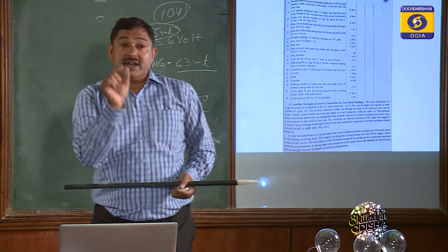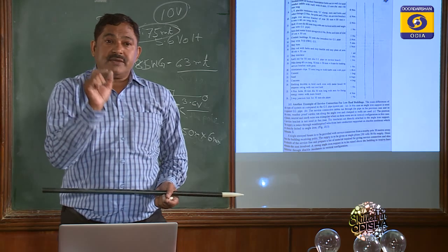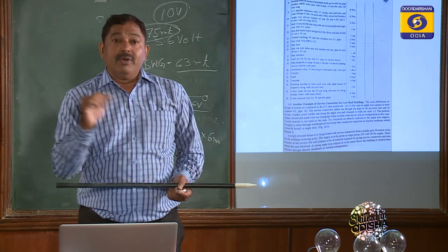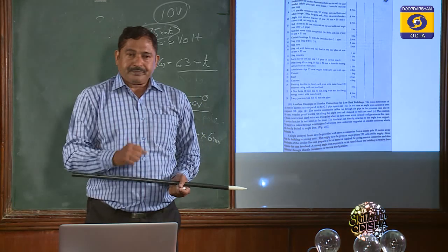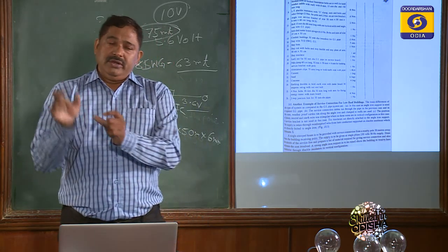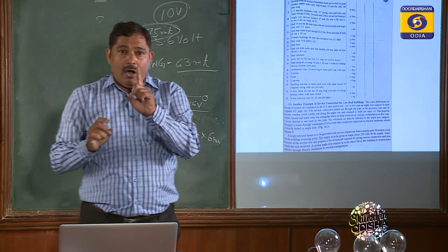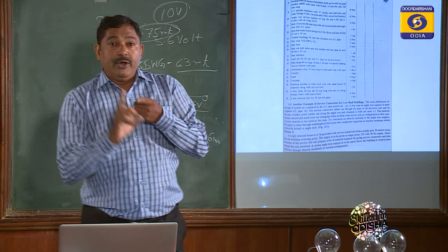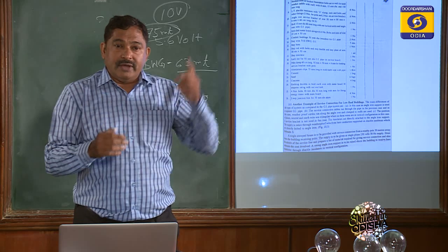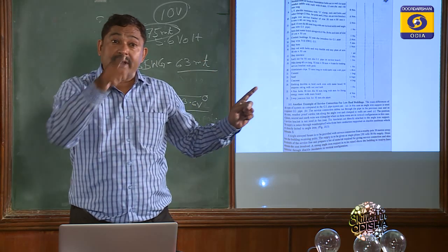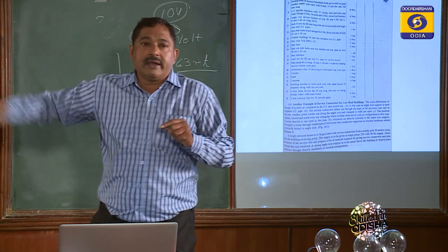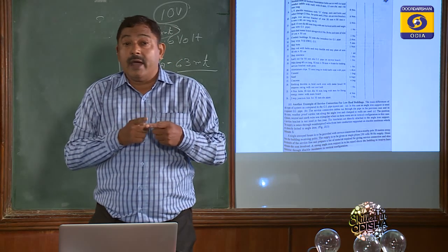There we have to give the RCCB facility. Nowadays this RCCB facility with MCB is used because in case of fire, this RCCB will trip. RCCB means residual current. Whenever we use MCB, we use a fuse also, because MCB operates for over current, but fuse operates for fault, short circuit. The moment there is a phase neutral short circuit, the fuse will go first. MCB will take time. If you do not have a fuse, only MCB, then the entire wire cable will burn, because the MCB will take time, I tell you.